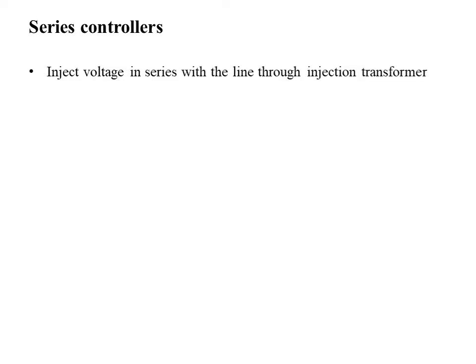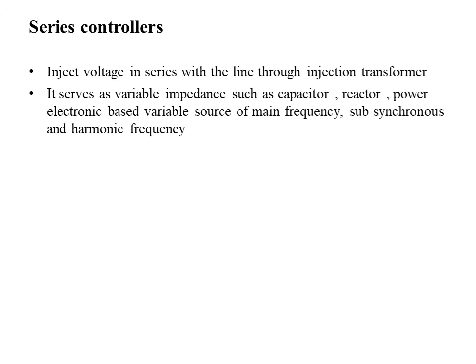So we'll start with basic rough ideas regarding the series controller. This part will be covered in detail in the next slides. Today we'll just have an introduction. Series controllers inject voltage in series with the line through injection transformers. It serves as variable impedance such as capacitor, reactor, or power electronic based variable source of main frequency, subsynchronous and harmonic frequencies.